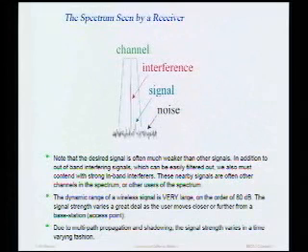And depending on the phase of these different paths, these different signals may add in phase or they may actually subtract. Let's say I'm communicating at 10 gigahertz. At 10 gigahertz, the wavelength's on the order of a centimeter. So if I just move a centimeter back and forth, I'm changing the phase of these different paths by an order of a wavelength, so that I can get a significant change in the amount of signal I'm receiving. This is called multipath propagation.